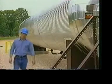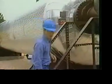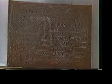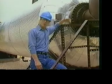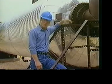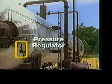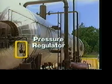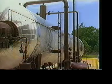Typically, heater treaters operate under working pressures of 5 to 50 psi. The maximum working pressure for a heater treater can be found on the manufacturer's information plate attached to the treater. All parts of the treater are kept at the same pressure. The treater should be equipped with pressure relief devices capable of protecting the treater if pressure reaches an unacceptable level. For example, pressure of the natural gas used to fire the heater treater must be regulated. If pressure exceeds acceptable ranges, the thermostat could fail to close, resulting in overheating of the treater.